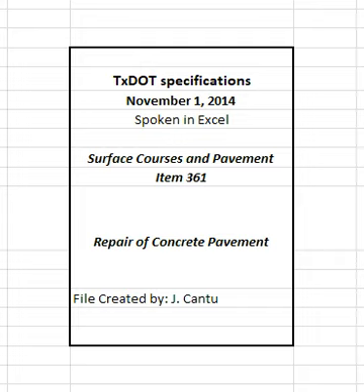Recompact base materials to the satisfaction of the engineer. Level the base layer with cold mix asphalt to the original bottom line and grade of the concrete slab before repair concrete is placed when shown on the plans. Place concrete directly onto the compacted base layer unless otherwise directed.